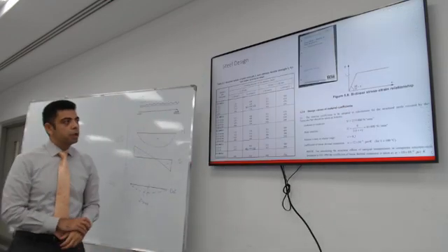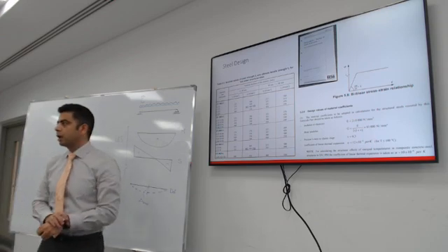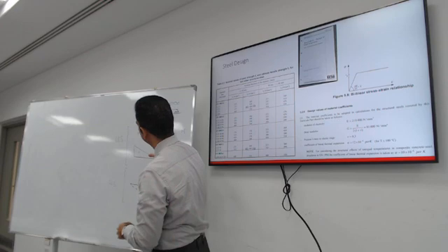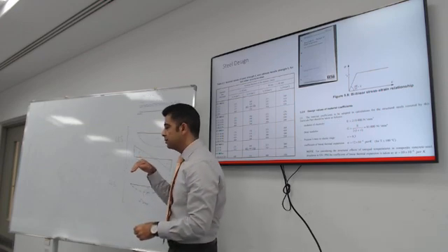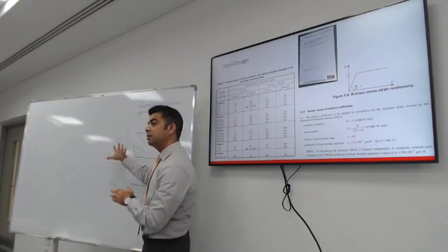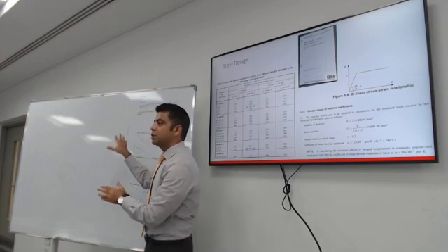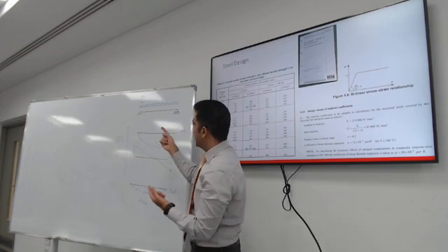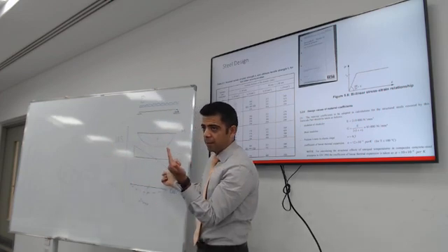Now, this is what we're going to do in the tutorial. I want you to start understanding the design of a beam as steps. First step, I will check the ultimate limit state, which has to do with the ultimate limit state factors. That involves checking for bending capacity and shear capacity.